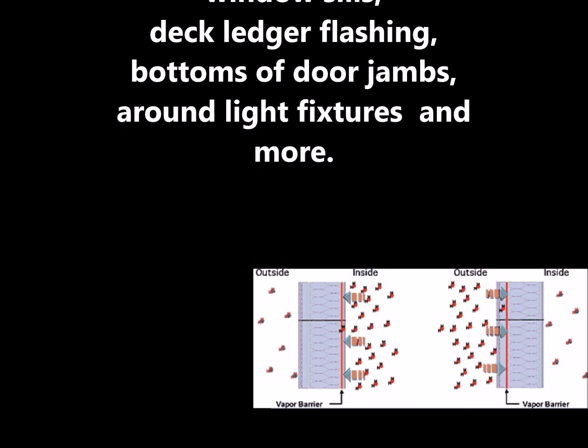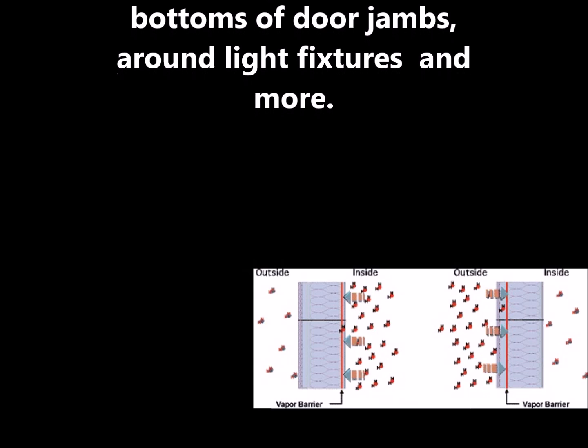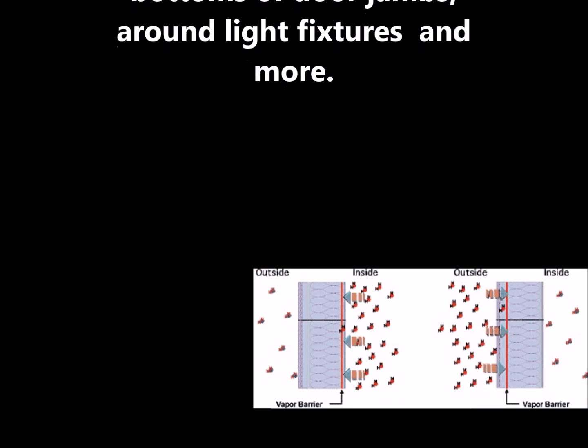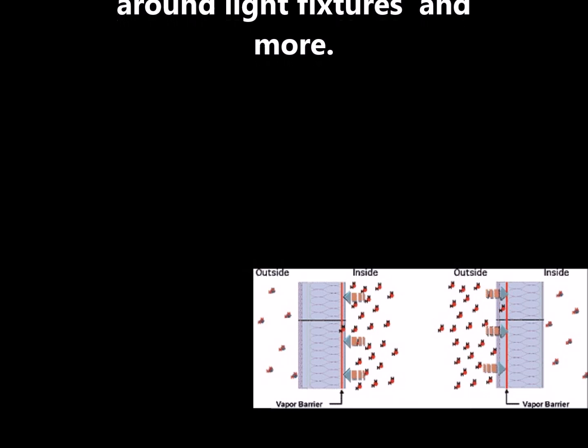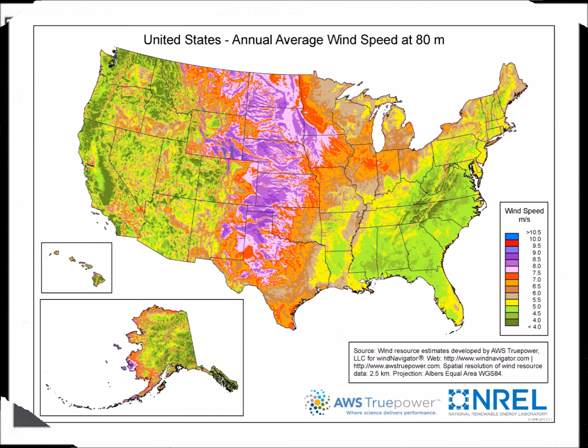So how does the added pressure of the wind affect moisture intrusion? When you're performing an energy audit, always pay attention and look at all the factors involved. Wind will produce a positive pressure on one side and a negative pressure on the opposite side. You need to consider these effects if the house has a complex shape. If there's a windstorm, there's an imbalance of interior and exterior pressures. The wind pressure effects on a house must also be considered with regard to neighboring structures.